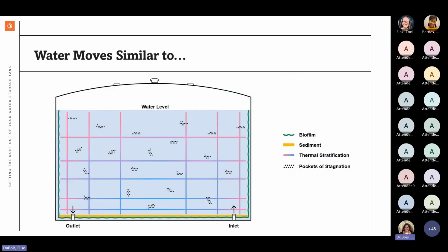So what's really happening in that tank? Well, let's take a closer look. First, we have stratification. So we know that the coldest water is on the bottom of the tank and the warmest is on the top. But did you know that as a shell heats up, the tank stratifies from the outside to the inside too? Keeping the tank's internal water temperature within 1 degree Fahrenheit or 0.8 degrees Celsius between the uppermost level of water and the lowermost is the industry standard for good water. Warmer water helps bacteria to flourish and disinfection residuals to decline fast.